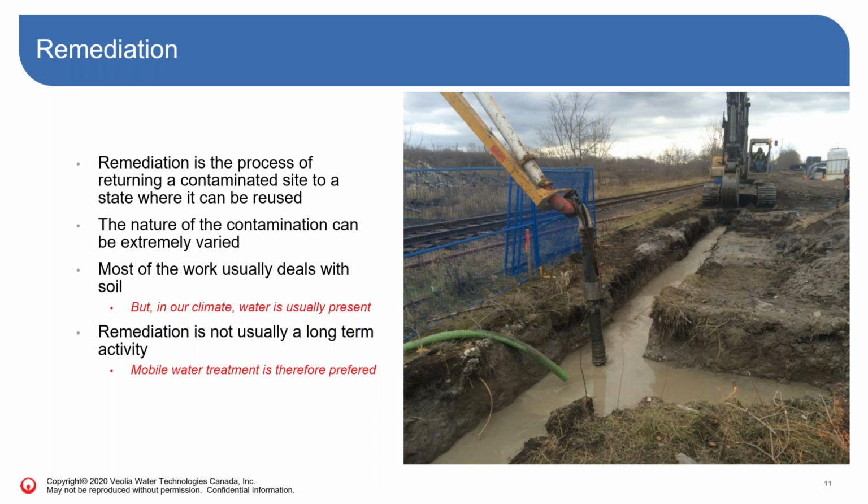Usually when we're talking about remediation, we're talking about ground remediation, soil remediation. But so why talk about water treatment in remediation? It's because in our climate, when we try to deal with soil, when we do excavation, we usually, as you see on the picture on the right, end up with water, and that water will pick up a lot of the contaminants on the site, so it will need to be treated before it is released into the environment.